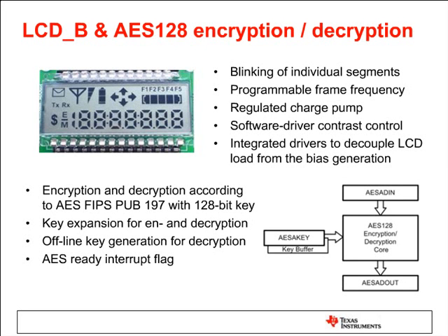It's good for the contrast and over temperature. You can actually blink individual segments. You have a copy of the LCD memory, which is kind of nice because you can blink between them, meaning you can blink it on and off, or you can blink a whole LCD screen, right? It's just two separate memories that you move between. So very, very nice LCD support using the LCDB.